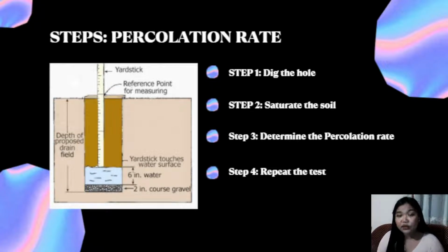Any value lower than 15 would mean that the untreated influent could drain away too rapidly and pollute the groundwater. A maximum value of 100 ensures that the soil's percolation rate is quick enough to allow the influent to disperse into the ground and avoid the system failing or backing up. Any value higher than 100 would mean that the untreated influent would not soak away fast enough for your system to be effective.